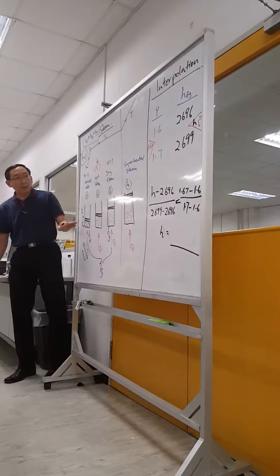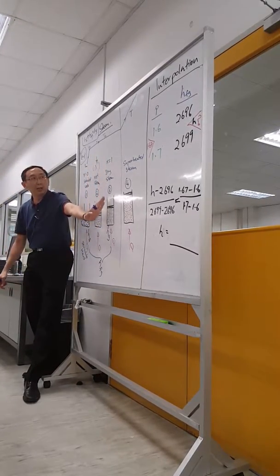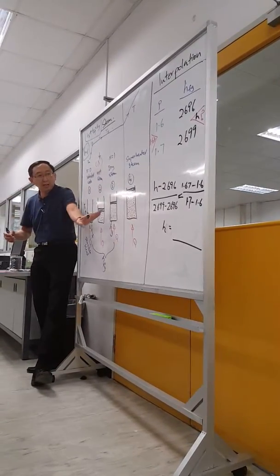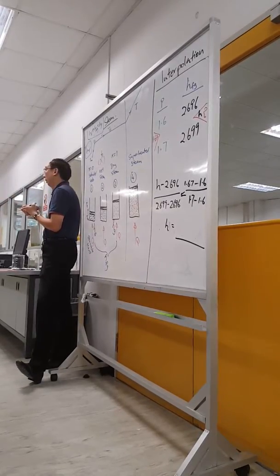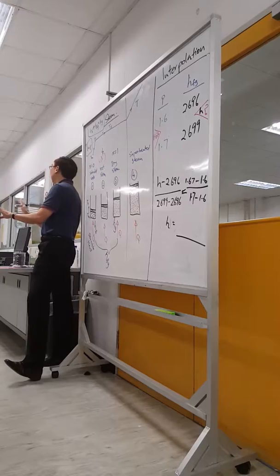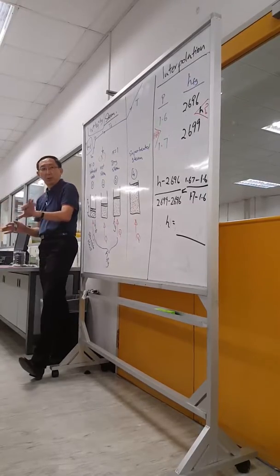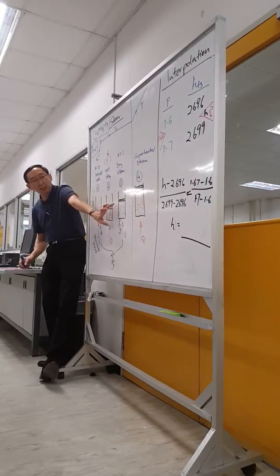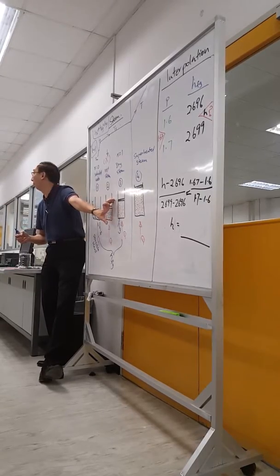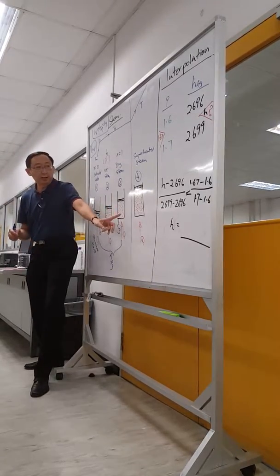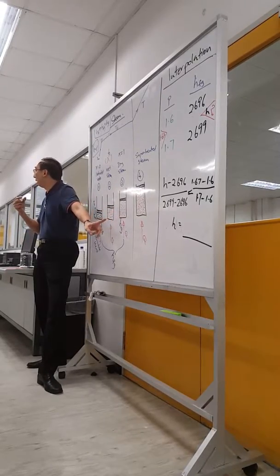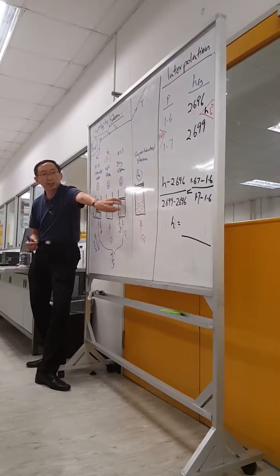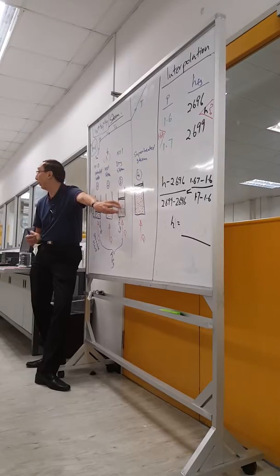Once I reach up to here, we term this as dry steam. Dry steam means that all the steam has turned to dry only, at the stage where it is totally dry. At this point, the steam is totally dry, but you notice that the volume is up. Of course, as it turns to steam and keeps on drying, the volume expands again. Take note, at this point when it is totally dry, it has this energy Hg. This energy means how much energy is inside all this dry steam. Enthalpy is the total energy.